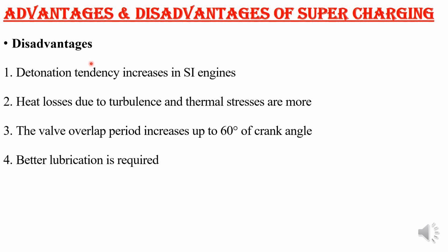Then better lubrication is required, because for the same quantity of fuel we are getting more power output, and so movement of the mechanical linkages will be more, and so better lubrication will be required. Then heat production is more for the same speed.